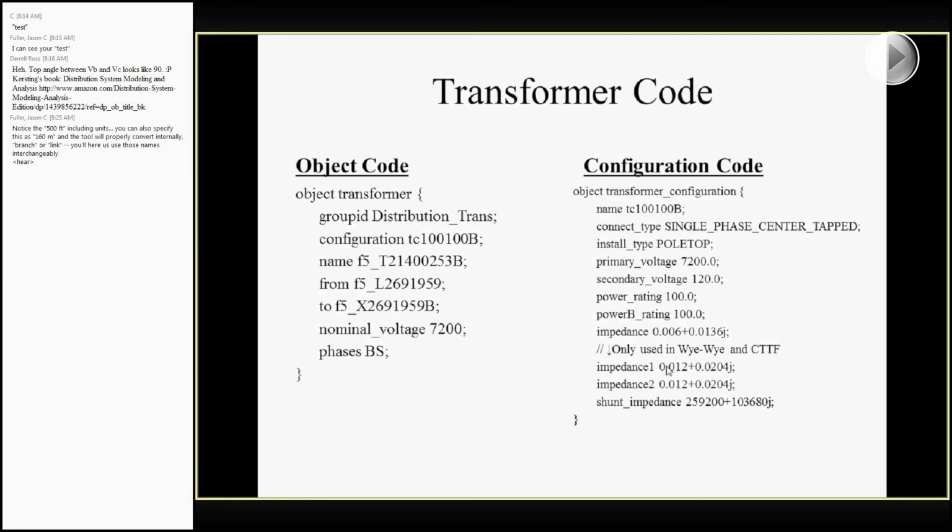One of the other fundamental differences between GridLAB-D's distribution solver and a lot of transmission solvers is that a lot of your transmission solvers are typically done in per unit. So everything is normalized against a common system base or a common system voltage, and you'll see values like 1 or 0.95 or anything like that.